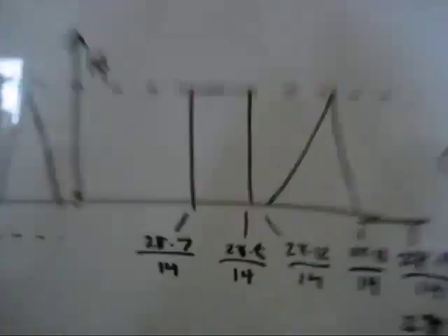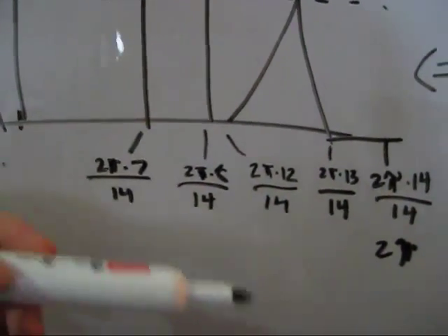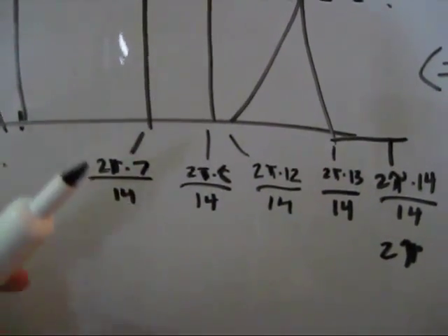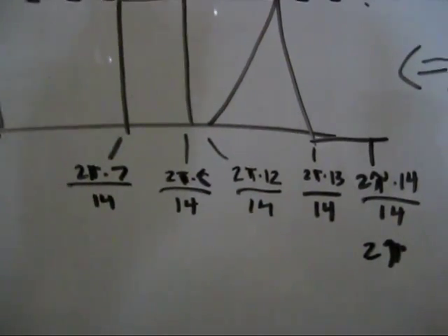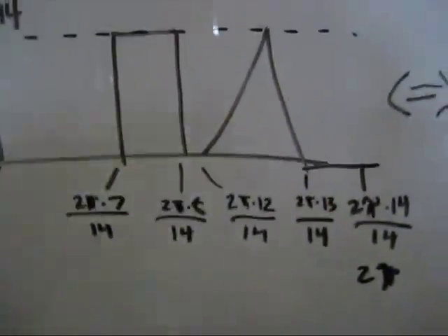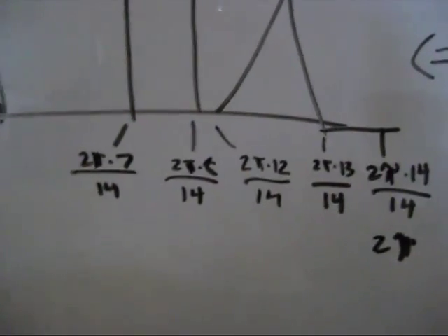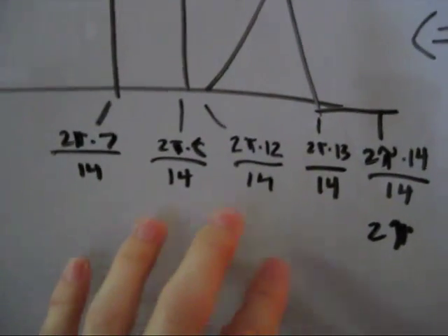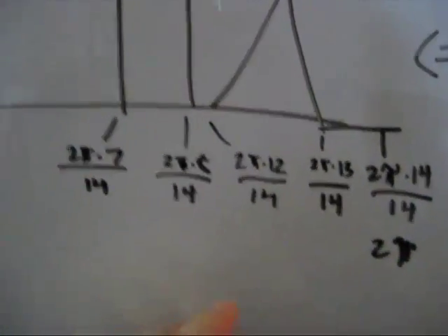So what you've got now is no information anymore as to what the real frequency is. That's why whenever you take a signal and you sample it and you just straight up do FFT, you don't actually get any real x-axis values. You look at it and you go, well, what's the frequency, right? That's because you haven't specified in your computational algorithm, not in FFT, FFT doesn't actually do this part for you, what the original sampling frequency was. But that's another topic for another time.